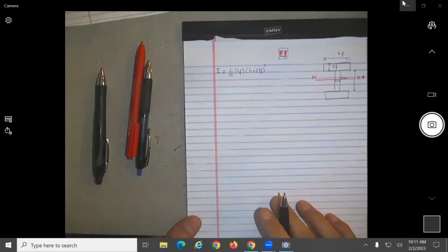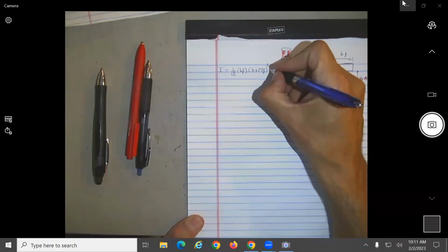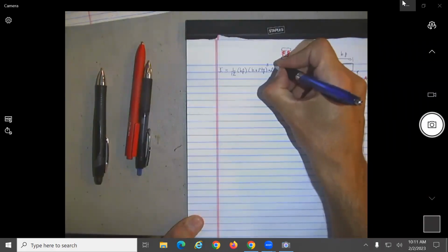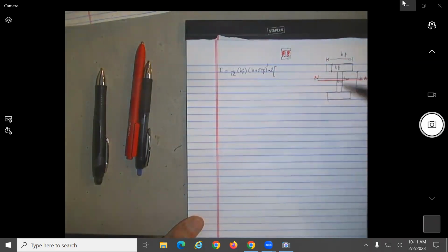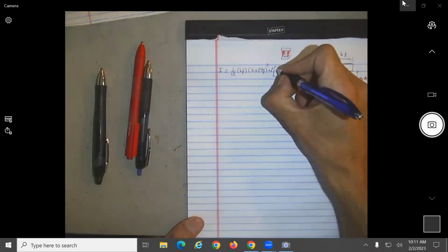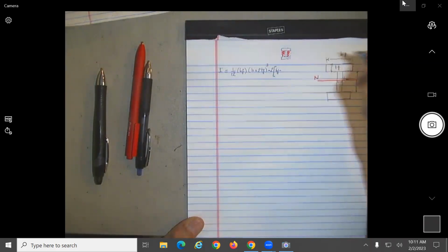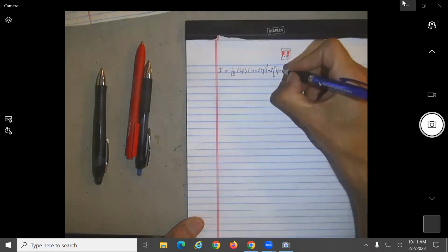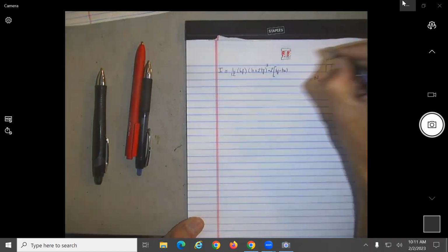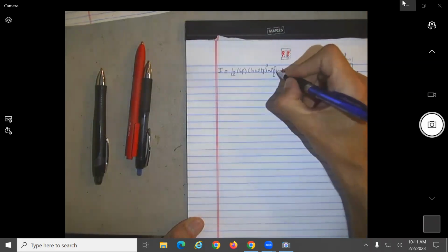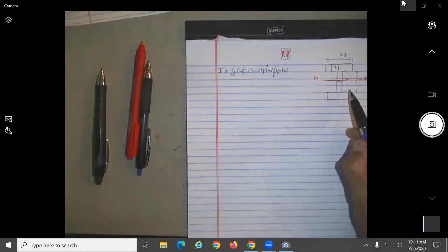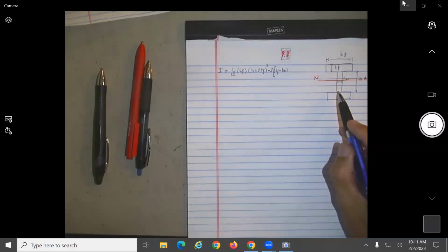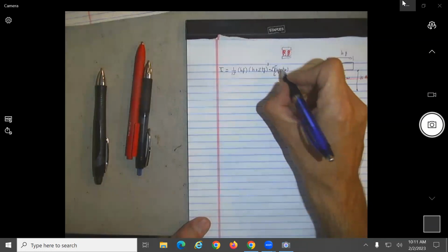And this one would be what? So let's see, minus 2, because it will be the two red areas, the two on the side. So what is the base over here for this one? It will be BF minus TW. But I'm doing twice, so it's BF minus TW divided by 2, on each side, no? So divided by 2.